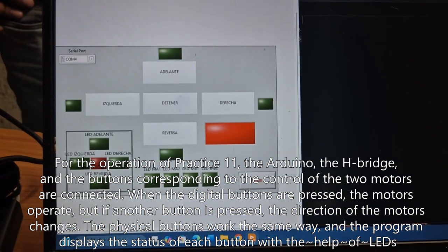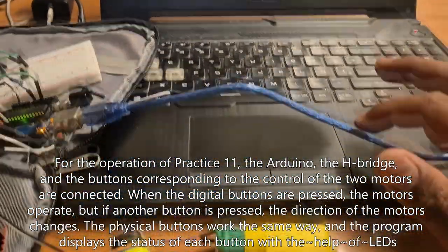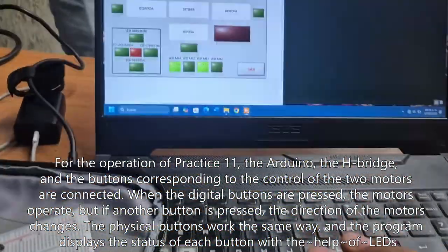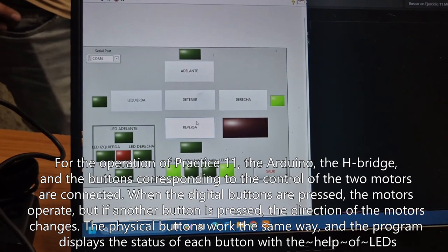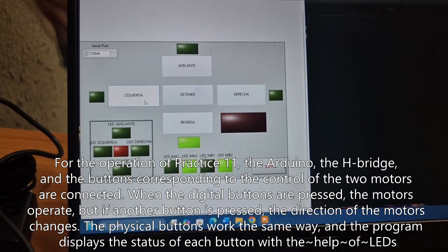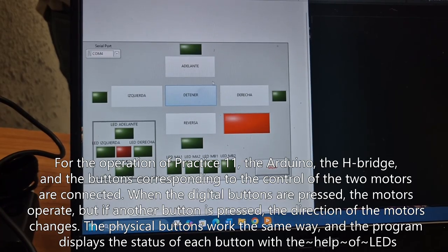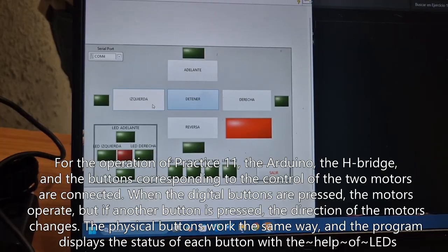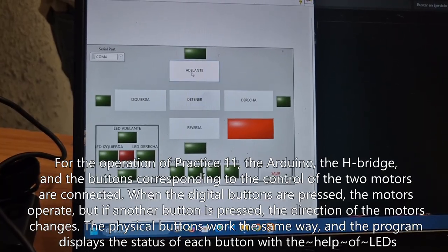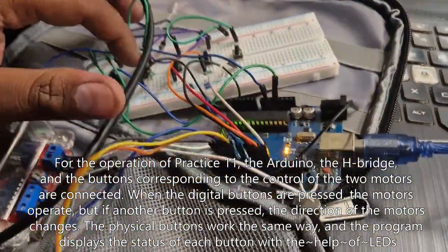For the operation of Practice 11, the Arduino, the H bridge, and the buttons corresponding to the control of the two motors are connected. When the digital buttons are pressed, the motors operate, but if another button is pressed, the direction of the motor changes. The physical button works the same way, and the program displays the status of each button with the help of LEDs.